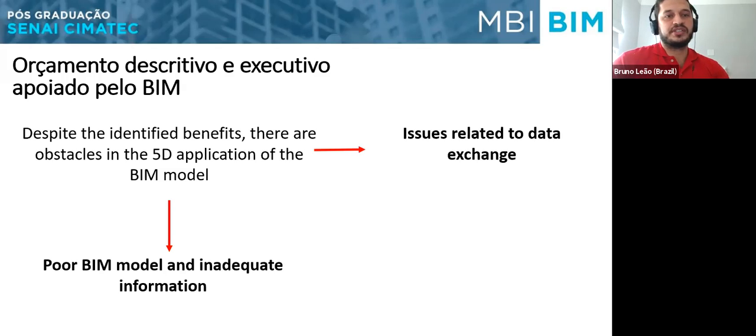Issues related to extended data: if we are talking about the use of more than one software, like Revit or Solibri, or ArchiCAD and Solibri, and even if we are talking about IFC, we have the problem of data simply disappearing in the process of closing one software and opening the other. That's one problem, and actually that's one of the reasons why I prefer to use Excel instead of other software.